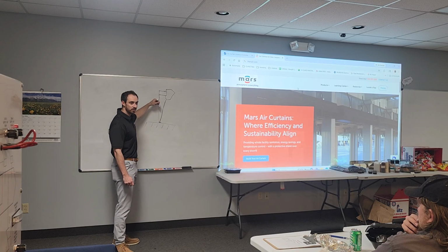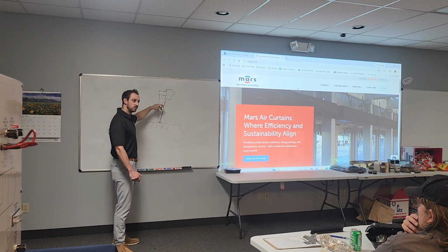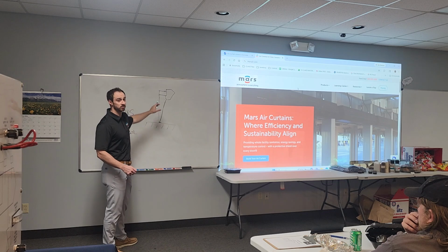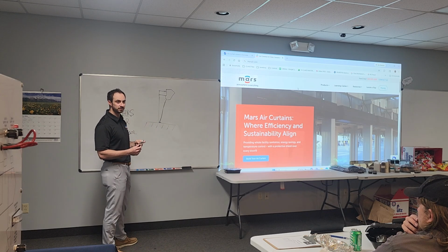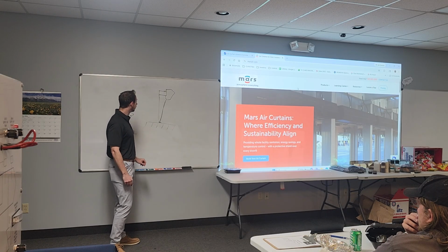If you wanted maximum coverage, the maximum benefit of the air curtain, you would need some sort of side baffle, which we do sell, like the bracket. We do sell side baffles as well, and they can also be fabricated in the field. Basically, you're taking that air curtain and boxing it on each side, to cover those gaps. Exactly.